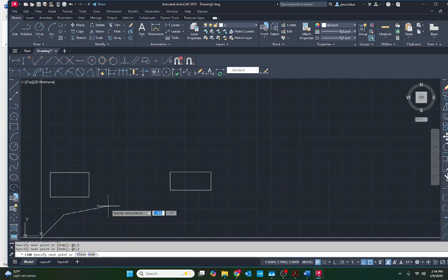So when you type here, you're typing dimensions that are relative. You can also type absolute. So if we know this point is 4, 4, if I wanted to make a horizontal line from that point that was 4 units long, the final point would be at 8, 4.